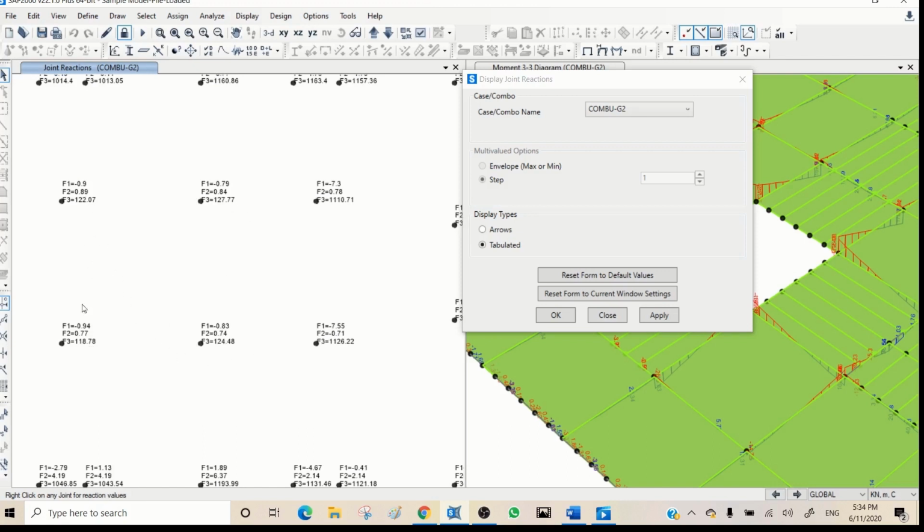Okay, probably we need to check the load transferring to the lift, because we have just one span miss in terms of the weight, so that shouldn't be that much difference. Probably loads are not being transferred to the wall. Again, we need to do all those troubleshootings, but sometimes it's long and we cannot accommodate everything in one short video like that. I'm just showing you the errors.